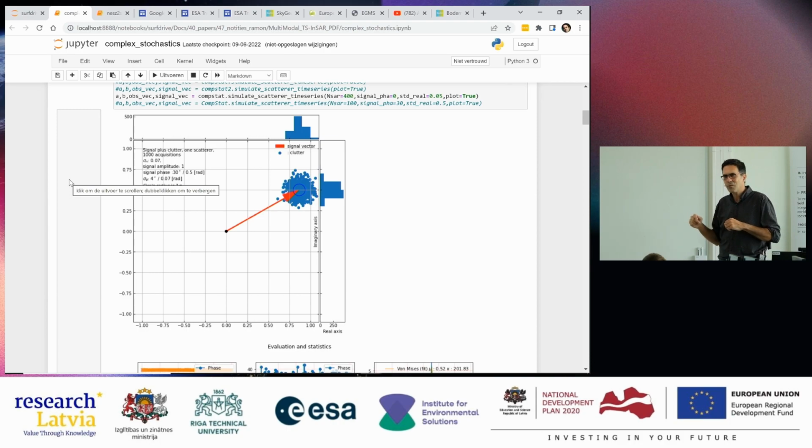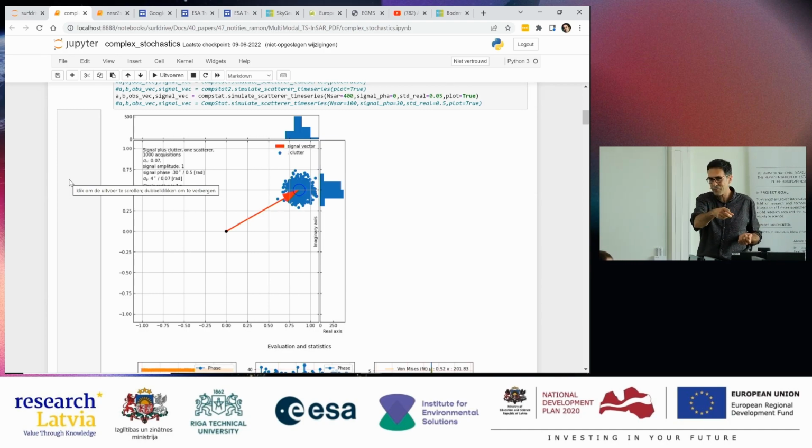How good is INSAR? How good is INSAR if you compare it with leveling? That's a silly question, because with leveling, we always know what we're measuring. We can touch it with our finger. But with INSAR, it depends what we want to see. If we want to see only the best points, it's okay. I just filter out the best points. You have a slider on your portal. You just slide that quality level to the right, and you get fewer points, but they will be much better. If you want to have more points, you slide that thing to the left, and you get more points, but there will also be more noisy points.